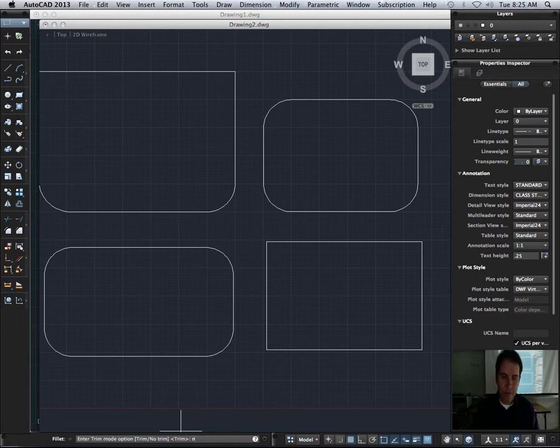I'm going to hit N for no trim, and then I'll hit my P for polyline again to do my entire rectangle here. I click on it, and you'll see now I've completed my command. I have my rounded edges, but it didn't trim away my outer points. I mainly show that to you because some people accidentally turn off their trim feature, and then they're wondering why it doesn't work. So that's how you turn it on and off. It's just hit the T for trim.